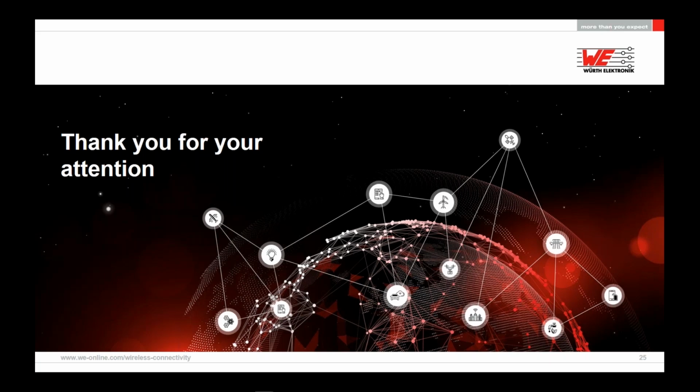So okay. I'm checking through the chats. There's one more I'd like to maybe just discuss with you quickly, is the overhead of our proprietary protocol. The header is in fact not very long. I believe it could be around about 10 bytes of data per package. Am I correct there, Matthias? Yeah, that's right. It depends on the features that are included in the protocol, but usually it's less than 10 bytes per packet, yes. Okay, and the complete package then could be roughly around about 250, 255 bytes of data, whereby bigger than that, you would then split it up and make smaller packages out of that. Exactly, yes.